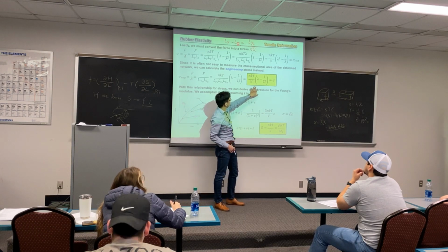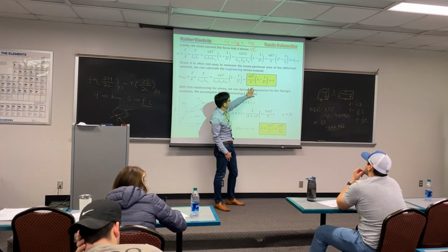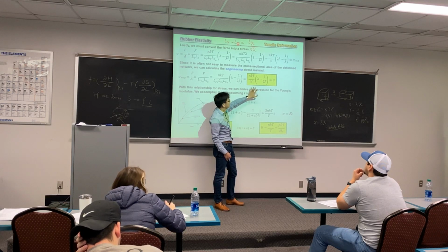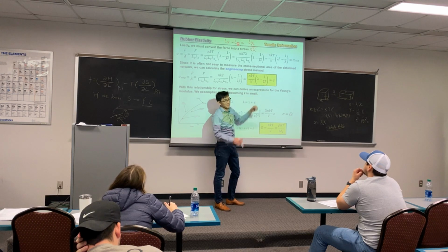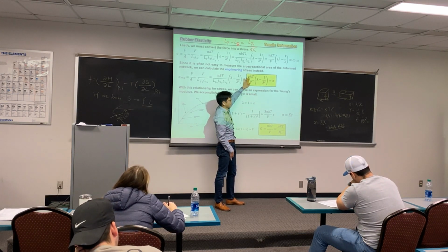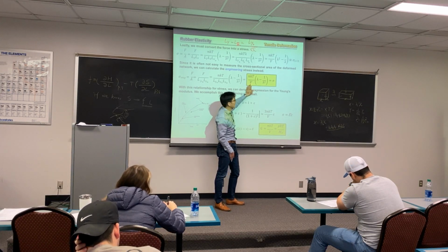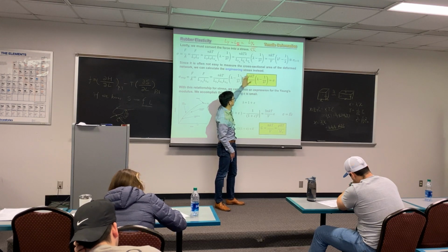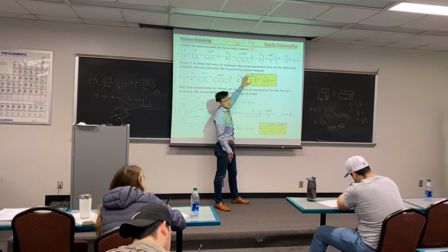Now, it's kind of very pretty. You only have 5 terms left in the equation. Your stress in an elastomer will be proportional to number of strands divided by volume. We sometimes combine these two together, called density of crosslink, right? Given a specific volume, how many strands.